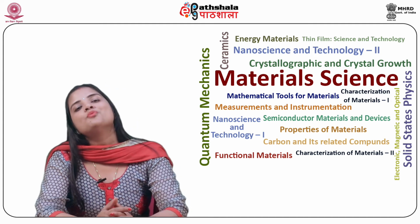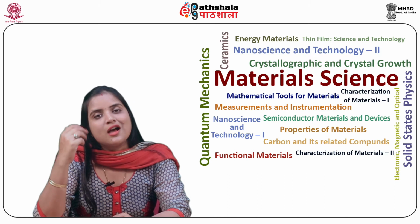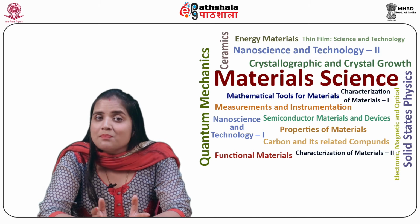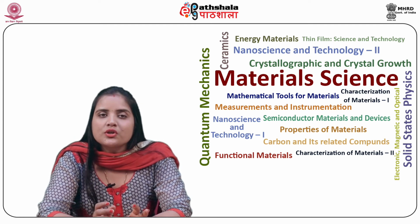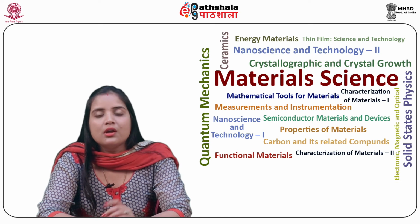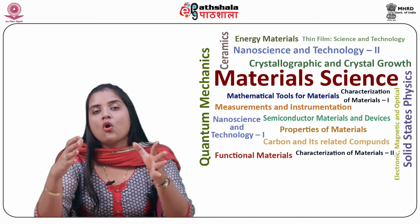Next we move on to monocrystalline silicon, that is monosilicon. These are more efficient and more costly than other types of cells. The cell's corners appear clipped like an octagon as the wafer material is cut from cylindrical ingots which are usually grown via Czochralski method. Solar panels using monosilicon cells are characterized by a distinctive pattern of small white